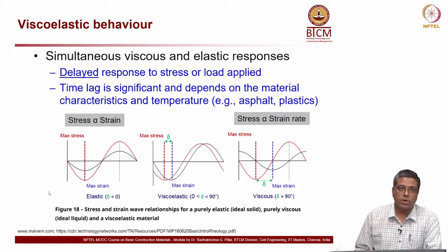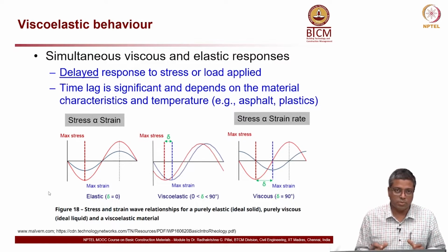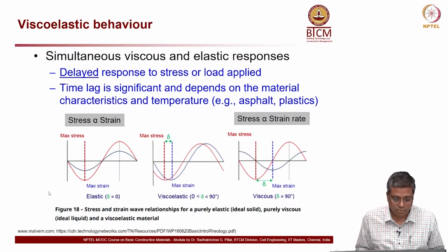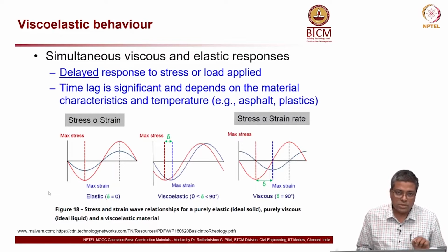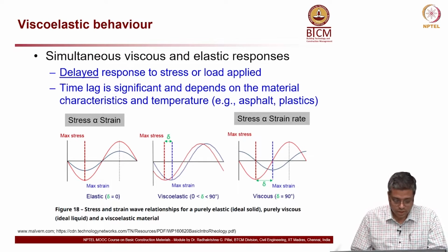So, what is viscoelastic behavior? This is essentially a simultaneous viscous and elastic response when materials behave in that way, and there is a delayed response to the stress or load applied. What it means is, let us say you look at the three graphs at the bottom. The first one is on elastic behavior, the second one is on viscoelastic behavior, and the third one is on pure viscous behavior. Now, in the first one, which is on elastic behavior, stress is proportional to strain, and